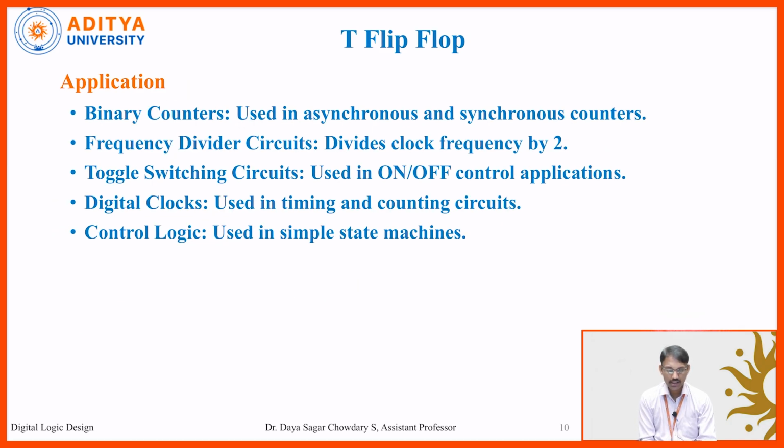Coming to the applications, binary counters are most of the time used in asynchronous and synchronous counters. Frequency divider circuits divide the clock frequency by 2. Most of the time this T flip-flop is used in a divide by 2 circuit. The clock signal is connected here, and at the same time the output is connected to the input with the help of an inverter, that means Qn bar is equal to T. So we can consider this circuit as a divide by 2 circuit.